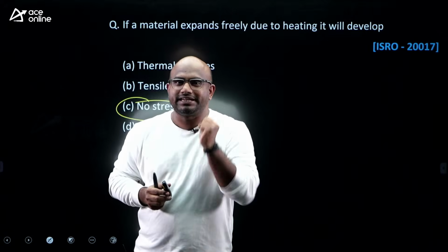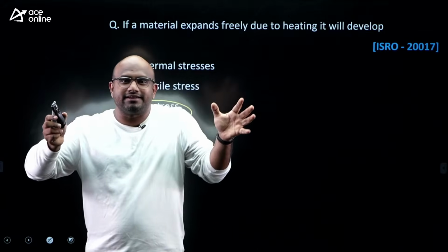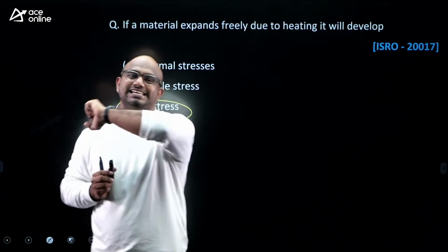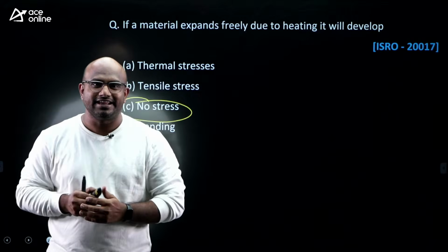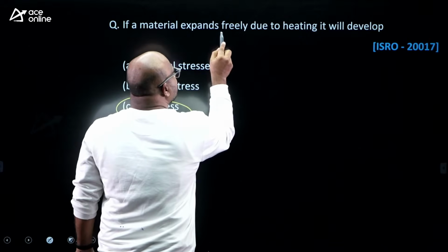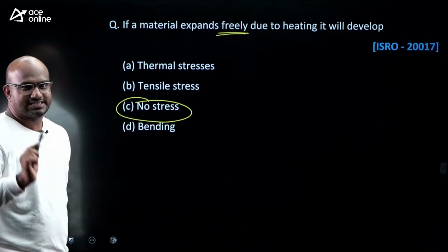Yes or no, sir? But here, what is the wish of a material? When I try to heat, it will expand. That is the wish of a material. If you restrict that extra expansion, guys, then stress will be developed. Are you getting an answer, everyone? Yes, sir. Here it is a completely free expansion. This is the keyword, guys. The right answer here is no stress, guys.